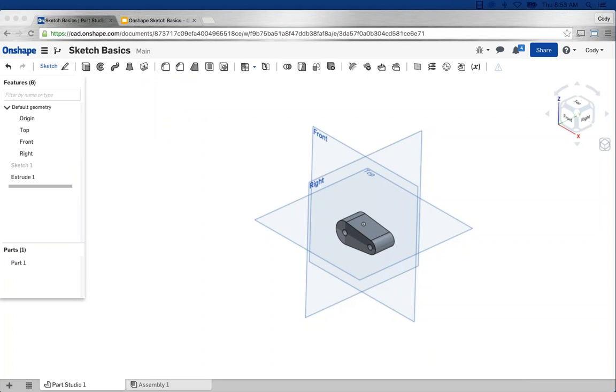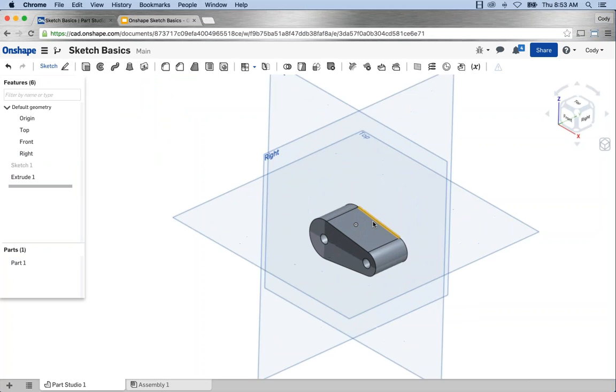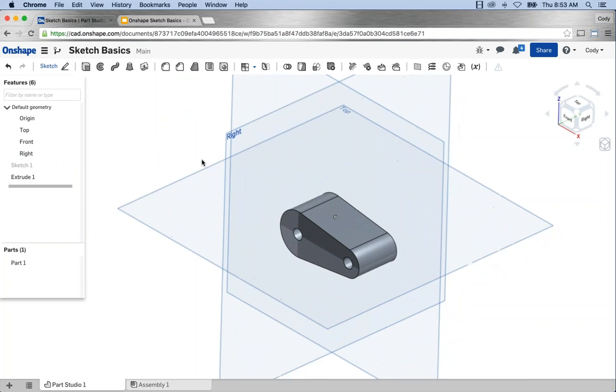A question that's come up concerning dimensions. Can two objects increase, decrease in size by dimensioning being linked to both objects? Absolutely. What I'd look into, I didn't cover it in this beginner's sketching, but I would look into variables. So I could create a variable, for instance, called bore, and set it equal to a value.